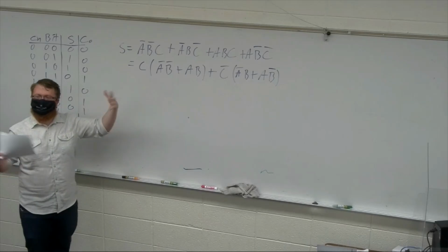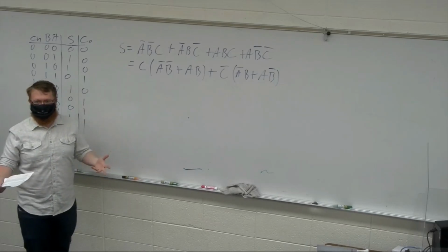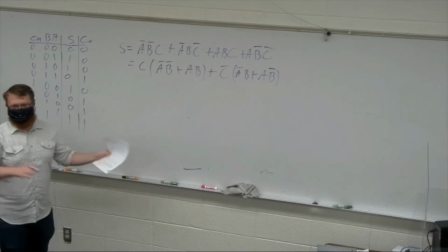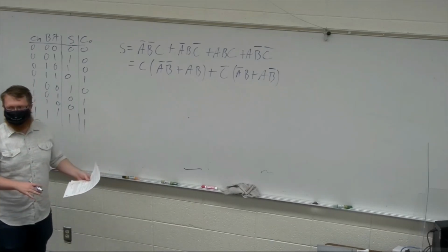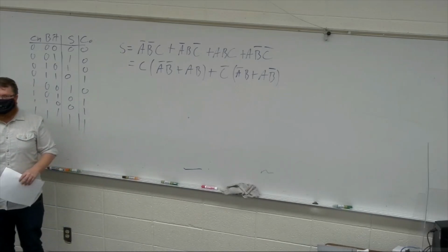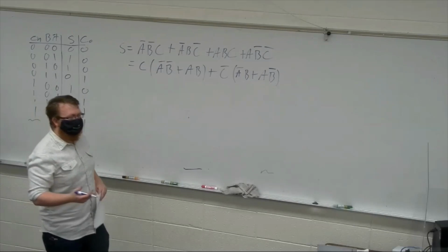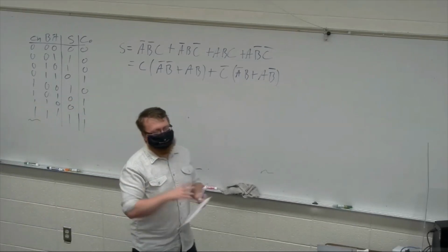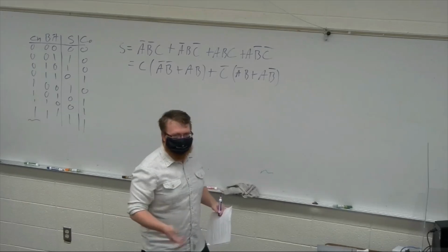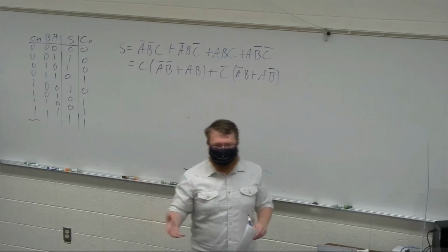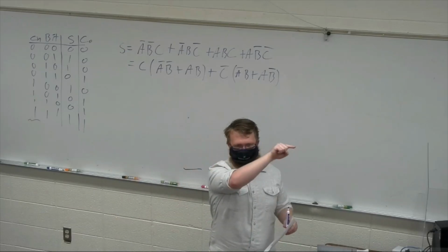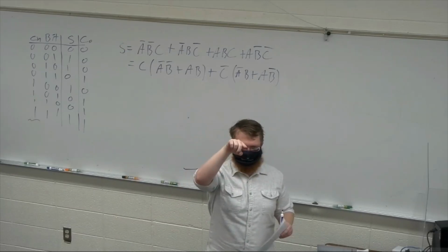We've done the full adder, we know that it's pretty much just an XOR operation. The whole point of this is to get to XOR, because this helps us when we start building up a more complicated adder, right? Because we know what a ripple carry adder is. And the ripple carry has, well, first off, does anyone not know the ripple carry? Everyone's familiar? You don't? So the ripple carry is just you take a full adder and then you string a series of them together where the carry out is tied into the carry in of the next.